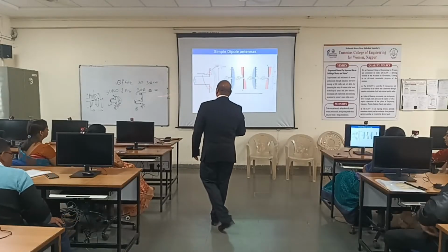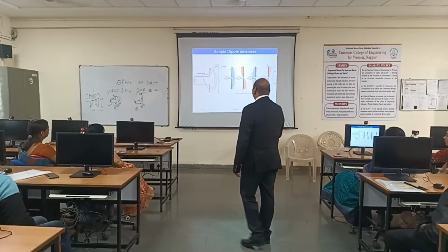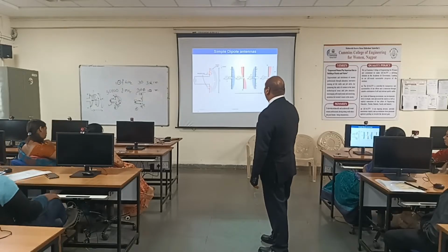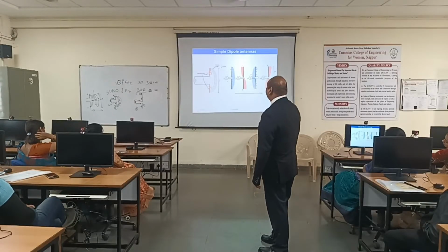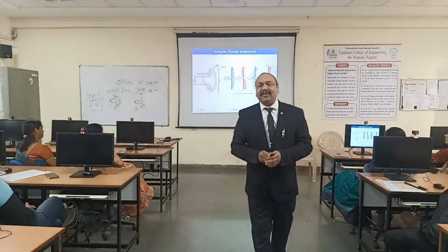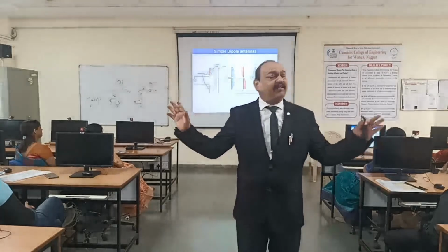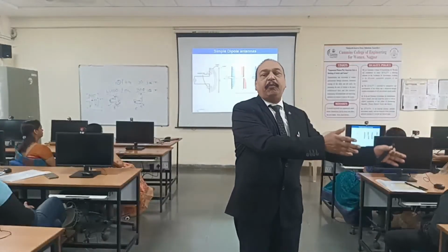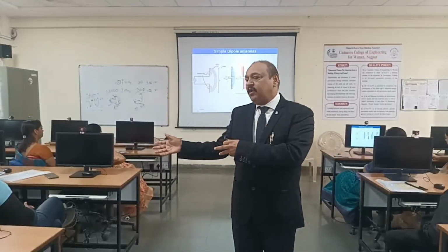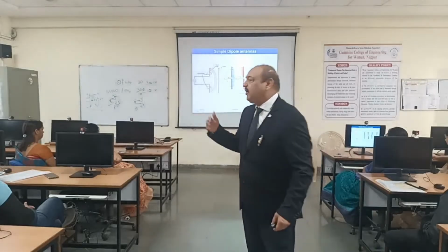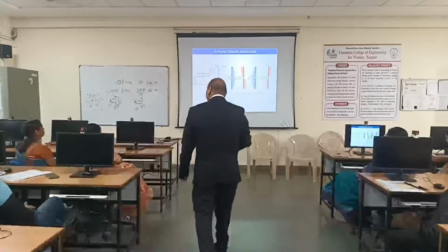Next. Here is the electric field line. At that time this is positive, this is negative, higher potential to lower potential, and this is the magnetic field. That's why an electromagnetic field will be generated. What is an antenna? An antenna is simply a transducer which converts one form of energy into another. When it is used as a transmitting antenna, it converts electrical energy into electromagnetic waves.